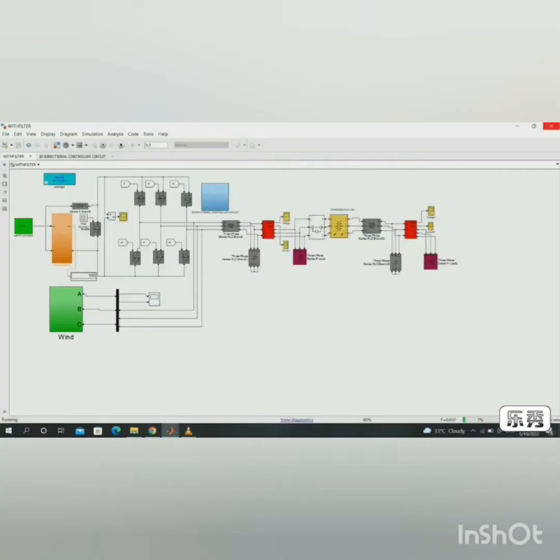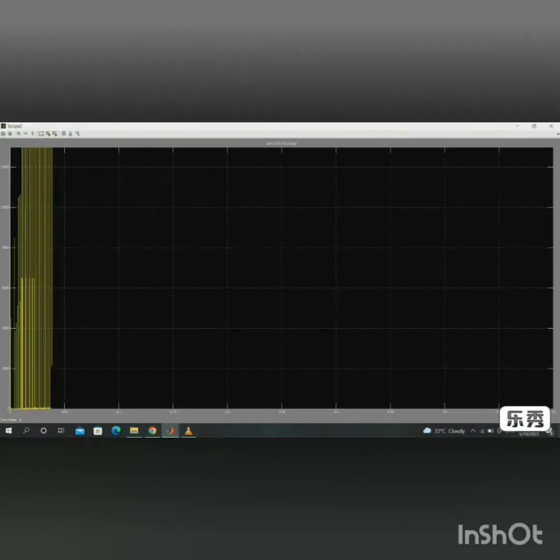We run the system to get the output from each solar, wind and transmission system by the values given already to each circuit system. After running, we get input voltage of 100 volt. Then the input solar PV voltage is noted, followed by output load voltage and output current. And then on the three-phase transmission side, we get the transmission output voltage and output current. With this, we get all the input and output results for the harmonic loss without filter design.